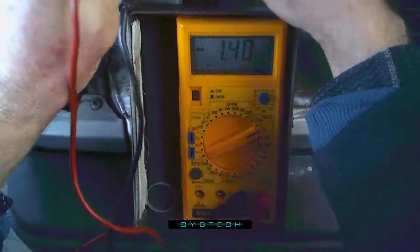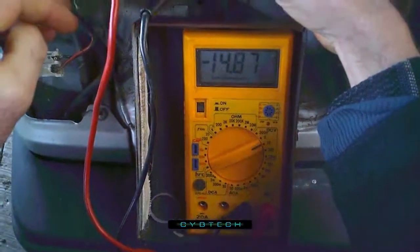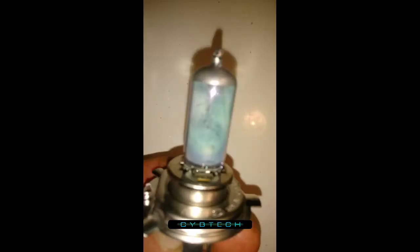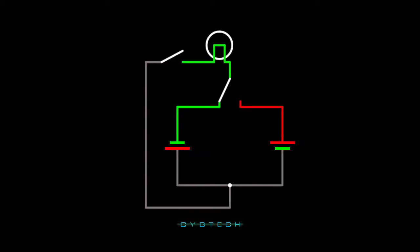I had to pinch myself as I thought, no, I'm not going mad. This is a negative chassis vehicle, not positive chassis. Was there something wrong with the circuit? No. A low beam filament on one of the lights had burnt out and so didn't work, but otherwise the headlights were working fine. I realised that this vehicle, being an older model, was manufactured when incandescent bulbs didn't care